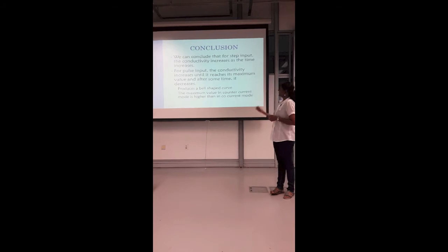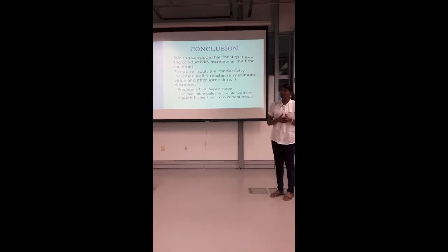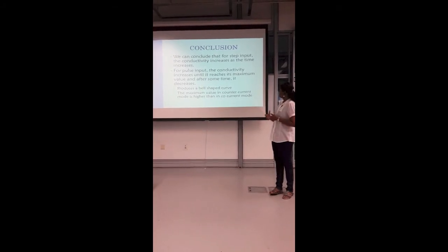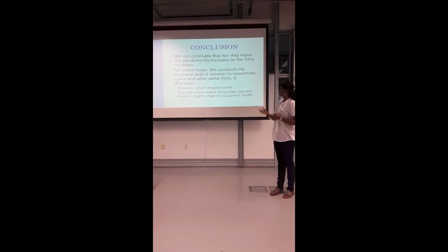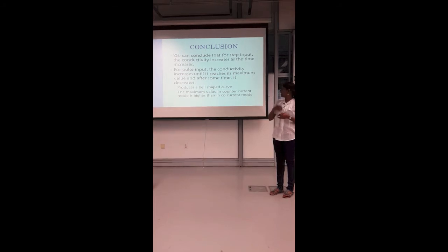Next, we can sum up the experiment by concluding that for step input, the conductivity increases as time increases. For pulse input, the conductivity increases until it reaches its maximum value, and after some time it decreases back, producing a bell-shaped curve, and the maximum value in counter-current mode is higher than in co-current mode.